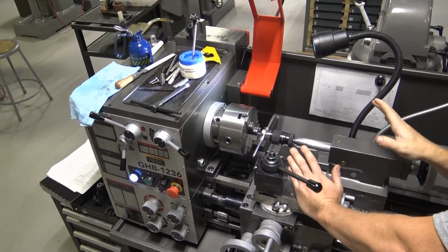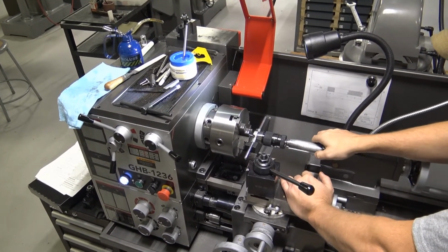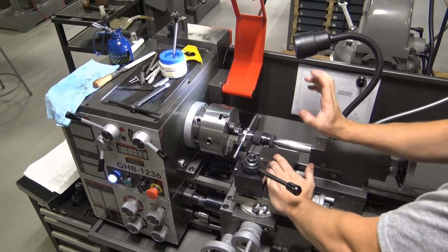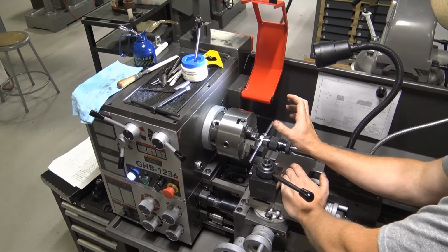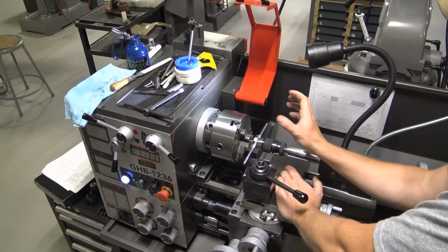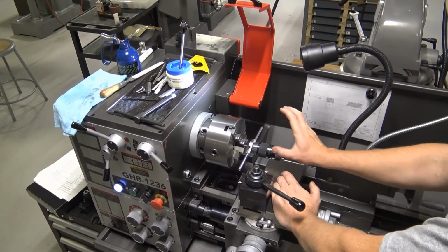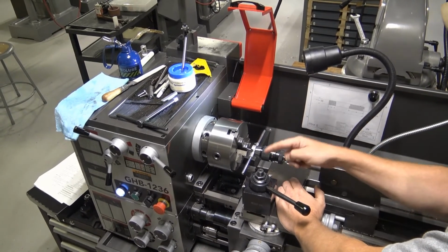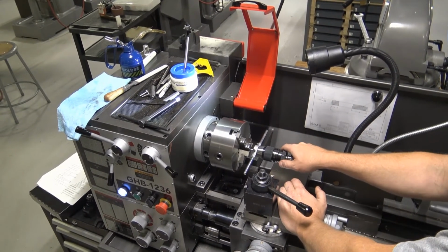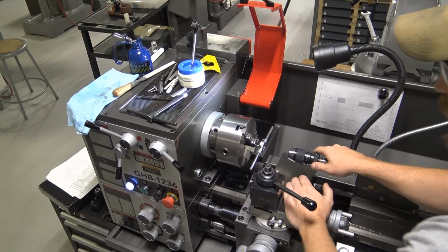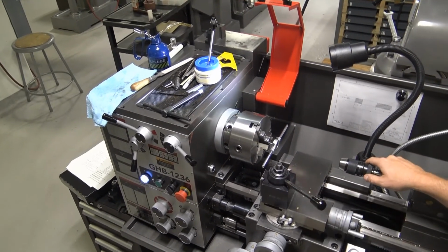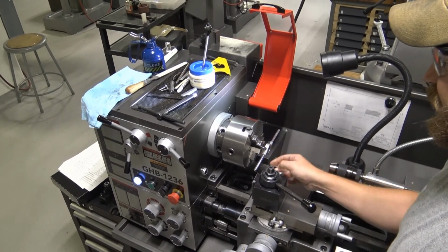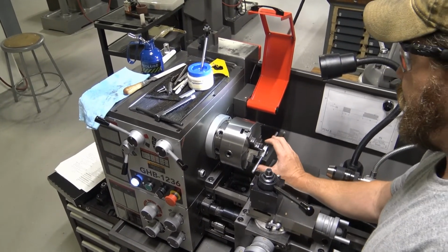So usually by the time you're into about your 5th thread, you don't have to really push on this so much, all right? Because now this thread is going down the shaft as straight as possible. And now just the cutting of the die will actually keep it on track, all right? So at this point I can actually move it out of the way, but you can see my die is now on there. It's cut 5 threads, all right?